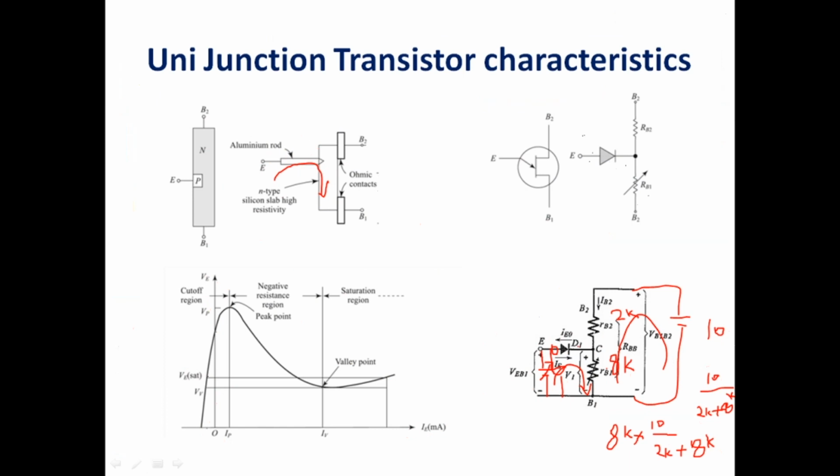But as usual, whenever a diode is not forward biased, a reverse minority current still flows. So whatever current is shown here is a minority current, almost like this. You can rely on this red line instead, as it is more appropriate. This small reverse minority current is flowing purely because of minority carrier flow. That will continue. Assume I am applying 1 volt, 2 volts, 3 volts. We have explained that this is not enough to forward bias the diode, so only minority carrier current flows.